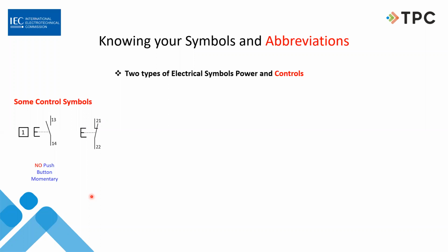But when I look at that symbol, I know. Okay. So here we have a normally closed symbol. And I've got the same symbol here, which is telling me somebody's going to push it. So that's going to tell us that it's a normally closed, momentarily closed push button. So kind of back to our stop start stations that we have on a lot of our equipment and machines.